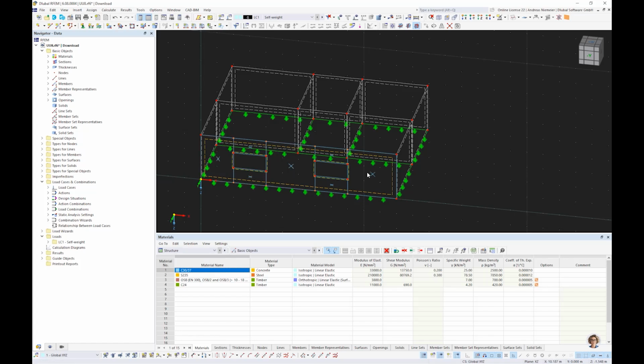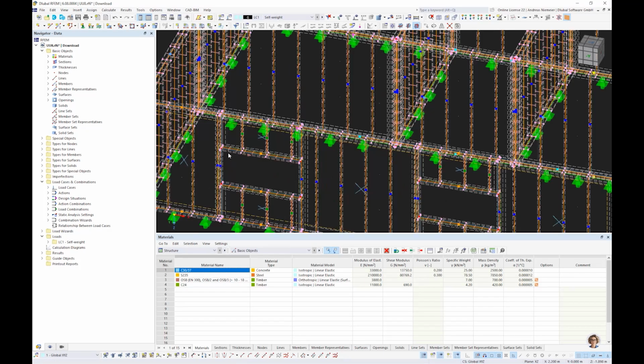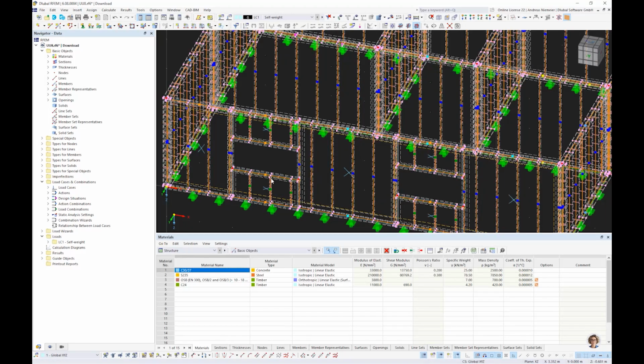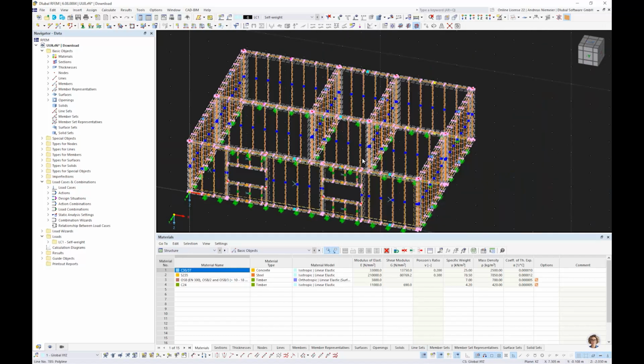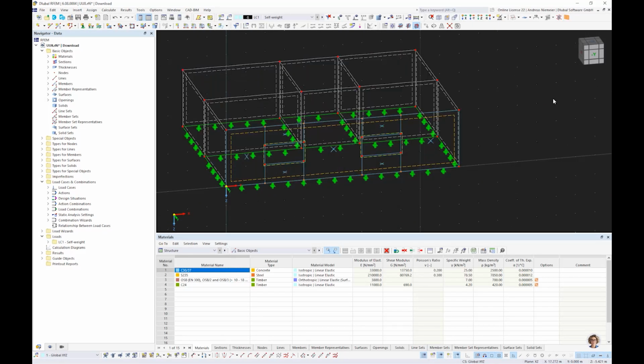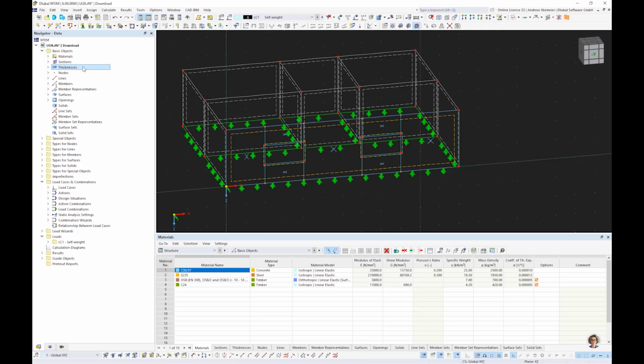And if I do this, the program is able to consider also windows with, let's say, a beam above and below, and also take care of the right distance of the vertical members. So it can really be a time saver, and you only define a few surfaces with a specific thickness type. Yeah. So this is one story of substructures.